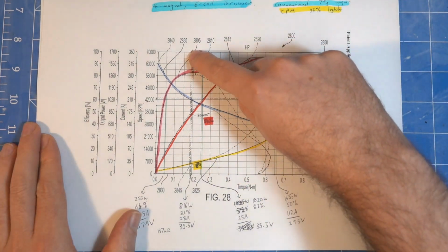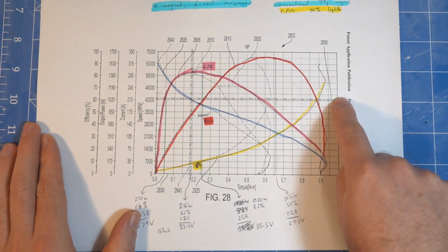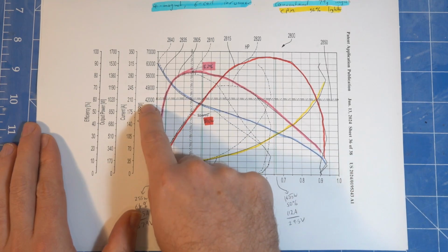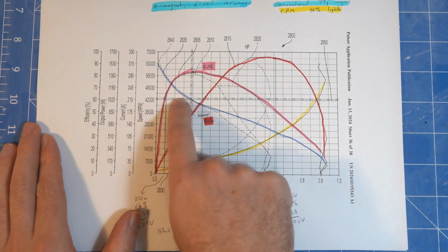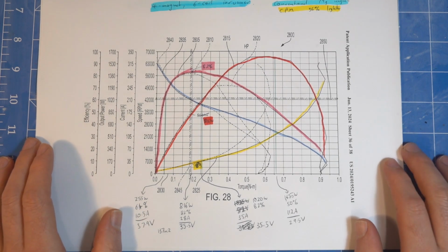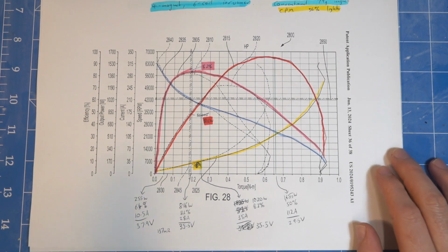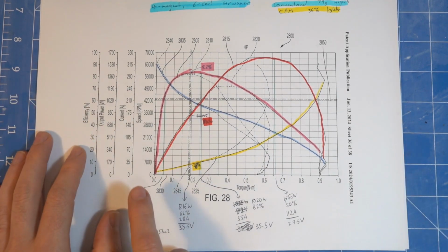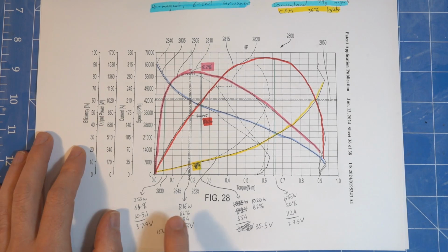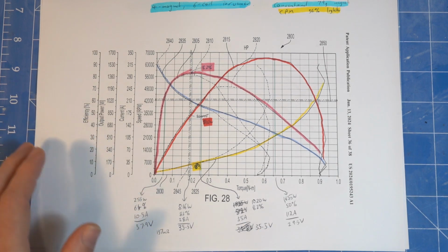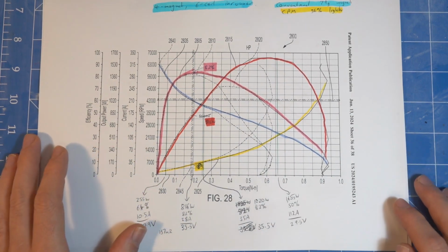So this one's got a very narrow operating region. So it's designed to run at that RPM. They even say so, that it's designed to run at 42,000 RPM. This kind of tool is most likely a vacuum or blower. They're the kind of tools that tend to run at one sort of set operating point. When we do the calculations, we actually get about 36 volts. So this is going to be one of their dual battery tools. I'm guessing the dual battery blower or dual battery vacuum.